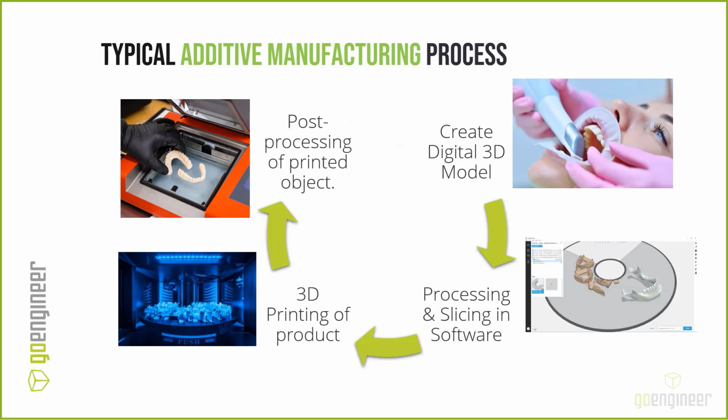After that, we go to actually the rubber meeting the road, where we print the 3D object. And then there's always going to be some type of secondary, post-processing involved, that includes removing the part from the build tray, any support material that needs to be removed, or excess resin that needs to be washed from the part. It's just technology and material dependent what that step is going to be. But the basic workflow holds true for all the different additive manufacturing processes to some degree.